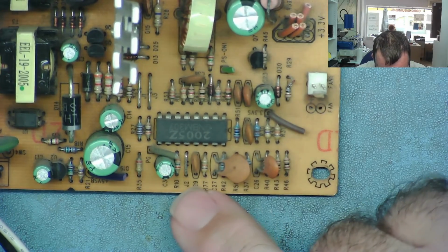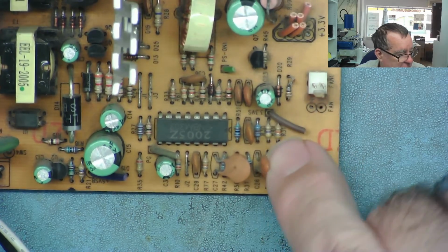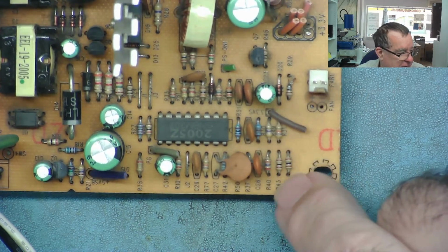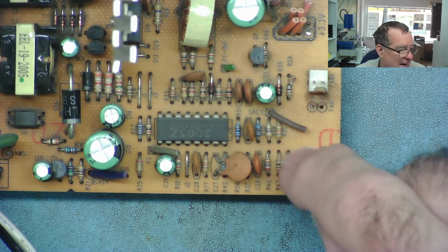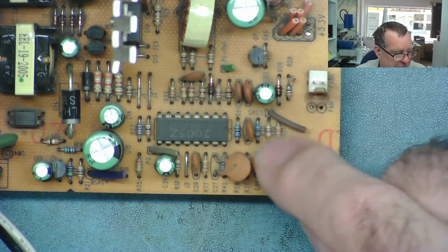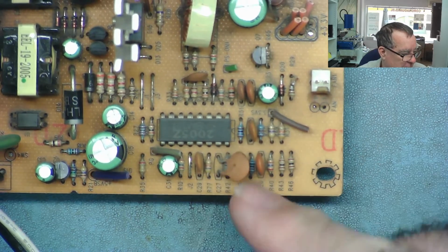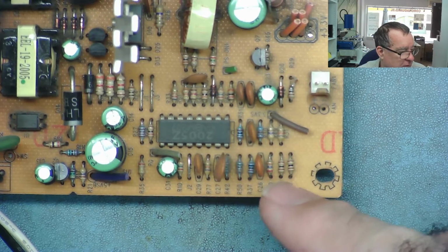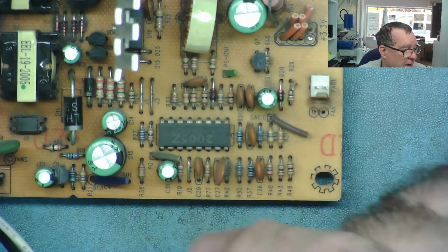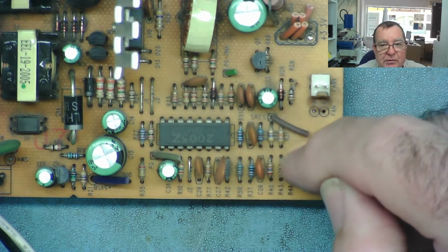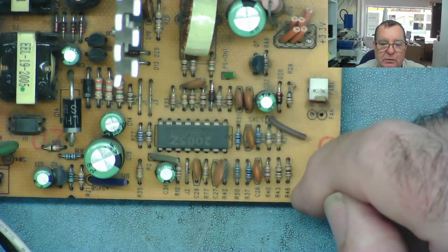And the way to determine that normally, if you see on this board here, all the resistors are marked R: R46, R43, R40. This is not the value, this is just the identification number of that component on the schematic. The capacitors are marked as C, so we have C27, C26. J for a jumper, just a bit of wire. If you see something that looks like a resistor and it's marked L, that will be an inductor.